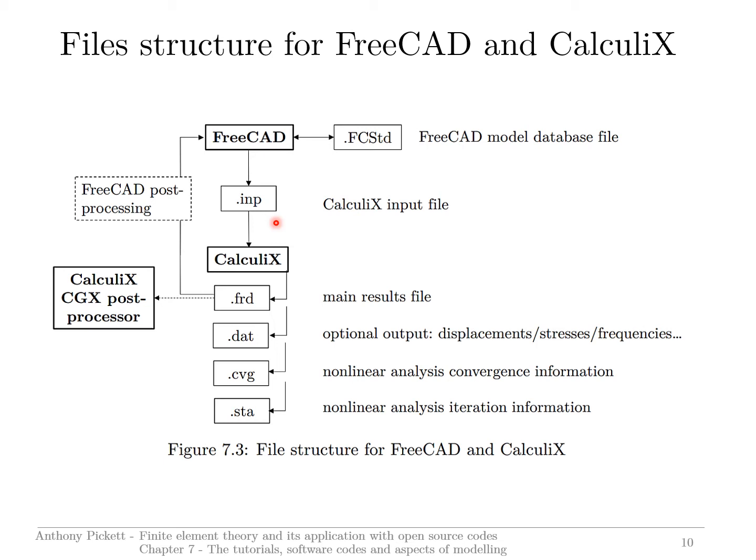And this is easily done actually, because FreeCAD has its own editor which you can open and directly introduce the changes you want. So this then is the file which is read by Calculix for doing the finite element analysis.